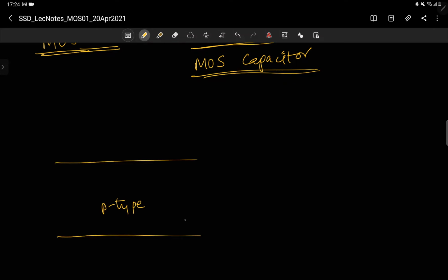It is of so and so thickness, and you actually pump oxygen at a very high temperature. So say if this is a silicon p-type semiconductor, this oxygen will interact with the surface, and then it produces an oxide layer. So part of it will be consumed, and then partly it will grow.